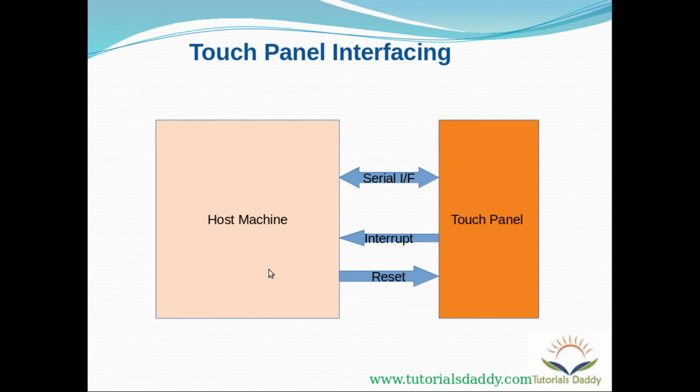And there is one other pin, that is the reset pin. The use of this reset pin is, whenever the host machine wants to start your touch panel, at the time of boot up or at the time of runtime, you need to bring up your touch panel, or you need to power on your touch panel. For that we need this reset pin, which will basically reset your touch panel. After resetting, your touch panel will boot, or your touch panel firmware will come into action, so that you will be able to see your touch panel is active now. And you have different modes by which you can set your touch panel.